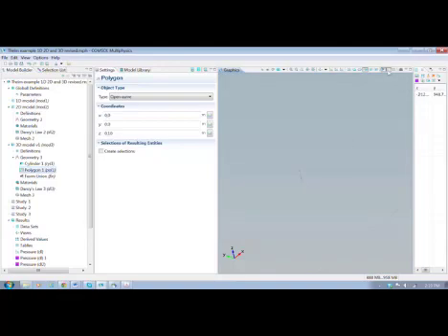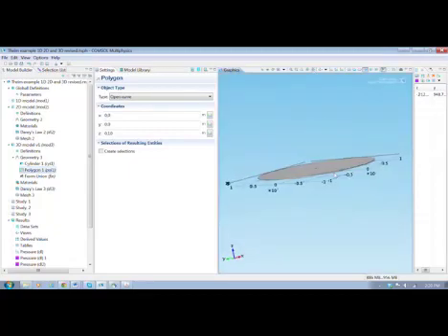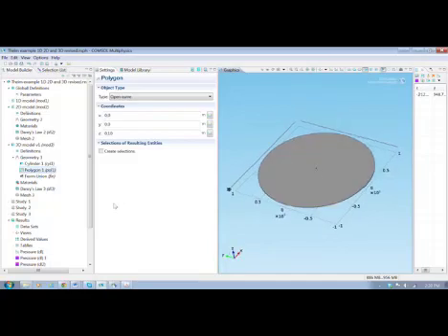That's making the upper surface transparent. Another way that we could do that, I'm going to make it opaque, and now I'm going to highlight the surface and then go to hide selected. And then view unhidden. One of the things when you use these hide and unhide, you hide an entity with this, but then sometimes it's confusing because things might not become hidden, or they may be difficult to see again. You should go and check out these settings if you have problems with that, and also sometimes reset is what you need. Okay, so we'll reset this, and we now are back to where we started. There's the geometry with this line source, what will be a line source down the center.